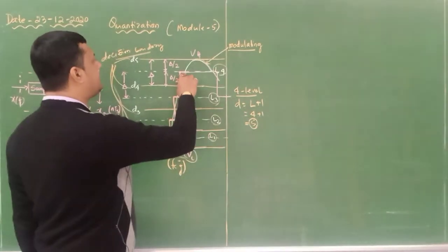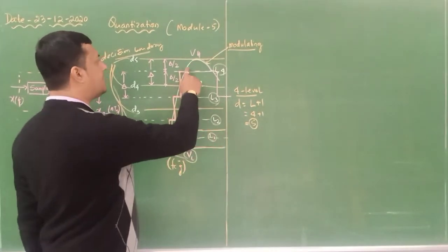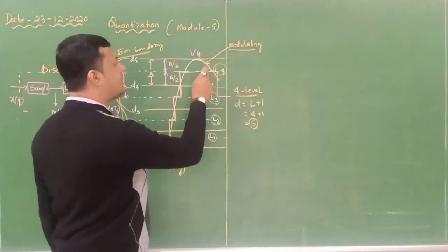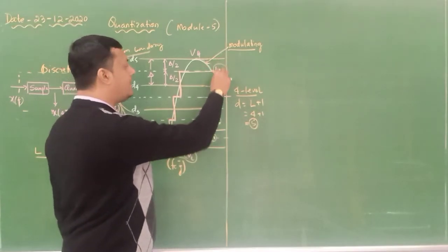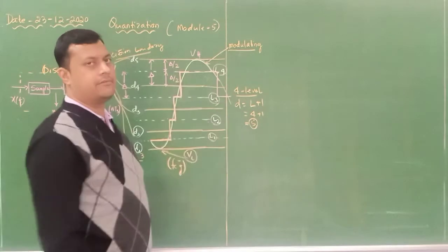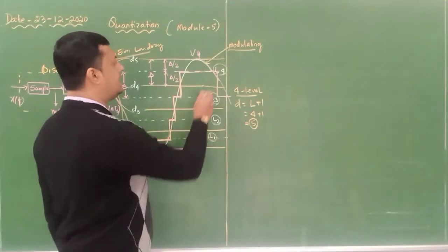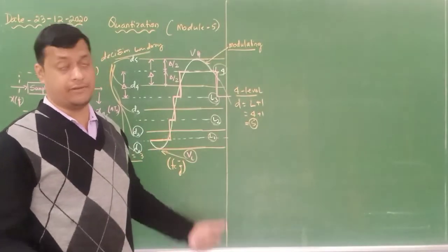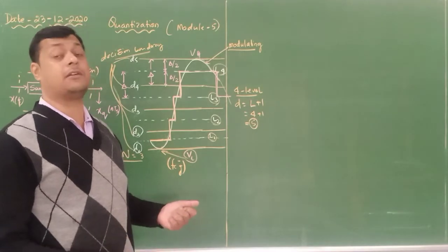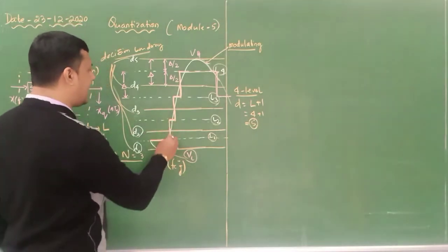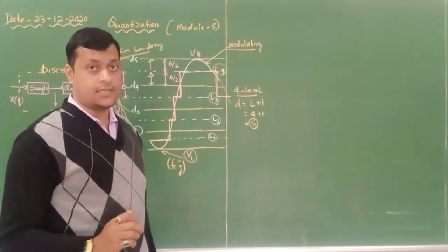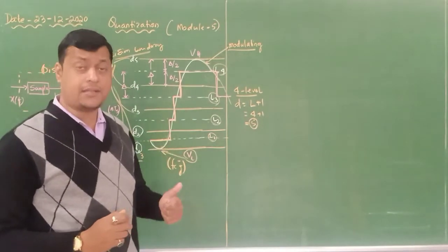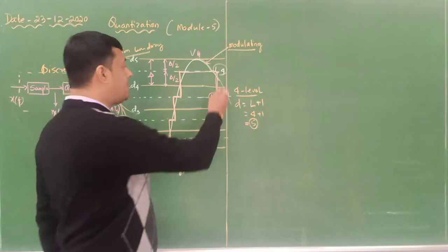Okay. Now, if the modulating signal is coming back from the higher value to the lower value, from level 4 now, you need to decrease to level 3 because the signal is decreasing. It will not follow this particular case, it will follow these pulses. So these particular pulses are nothing but quantized levels of a particular modulating signal. So these lines come under your quantizer. The quantizer comes into the picture when the number of decision levels, the number of decision boundaries, and the number of levels are identified.